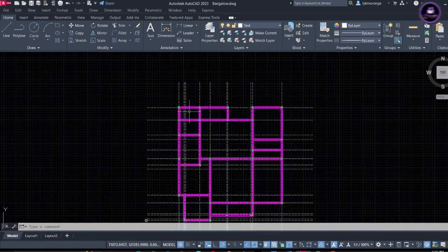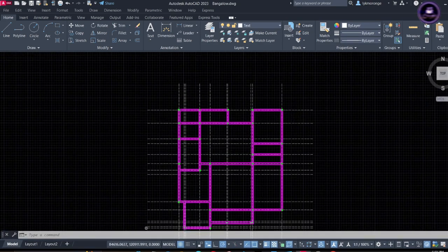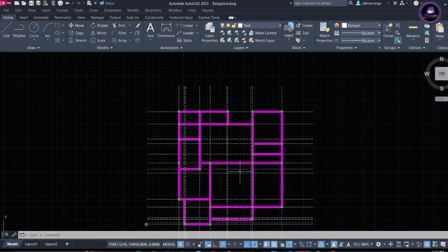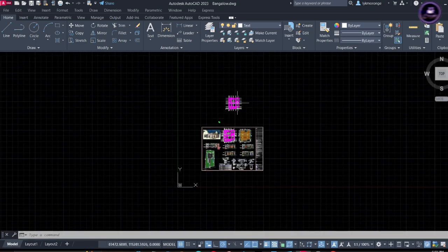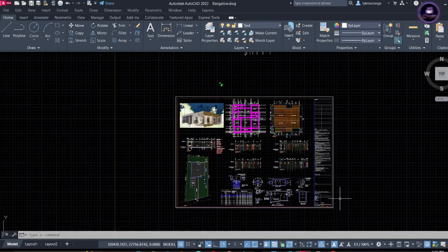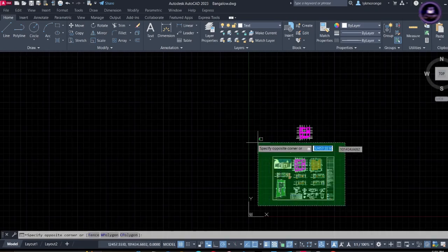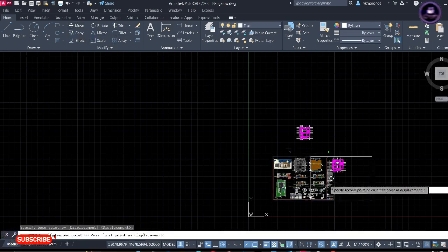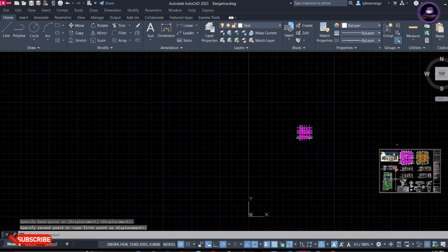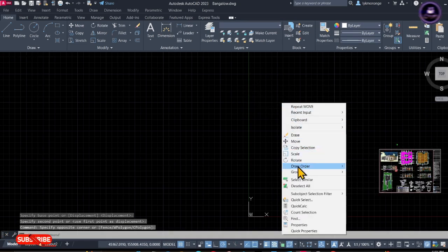So you can as well go ahead and name this panel like panel 1, panel 2, panel 3. But for now, I'm okay. I will just import it the way it is. So to export it, remember you should always copy this model closer to the axis. So what I'll do, I'll clear all this, copy all this, right click, pick move, just come closer here. So we have it there, and then copy this, bring it closer to the axis.